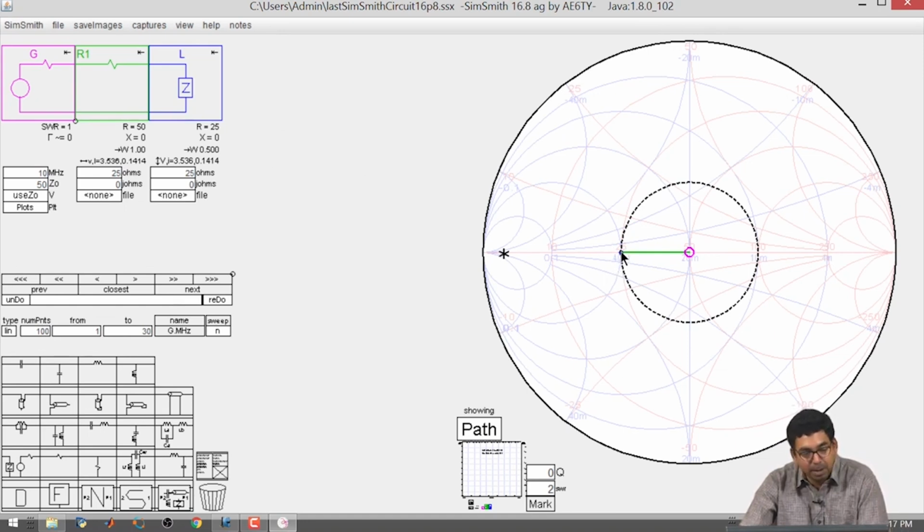The resistance is the green part, and this graph is very interactive. It shows that because you added the green part, it moved from the load to this point as seen by the generator. The generator is pink, corresponding to the pink color in the circuit. So, from the generator side, it sees that the circuit is fully impedance matched, and it has no reflection coming to the generating side at all. So, the standing wave ratio it sees is 1, and the reflection coefficient is 0.